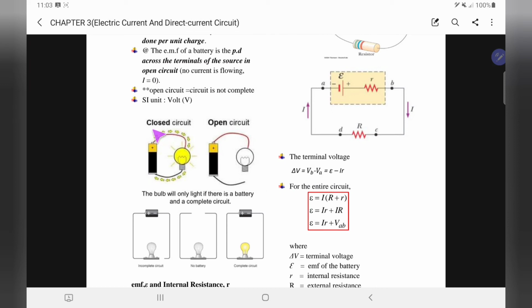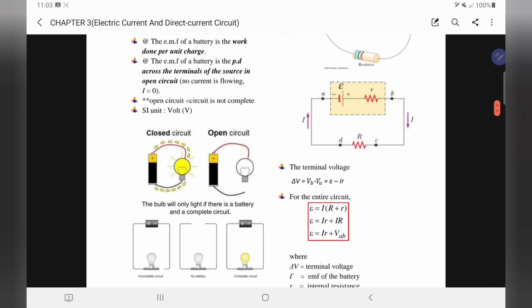Okay, so remember, for this situation, by connecting a voltmeter, the reading getting out is not EMF, because this one is connected to a resistor already. For the EMF, it should be when the switch is turned off, like this. Then we just connect to the voltmeter. The reading now representing the EMF of the cell.